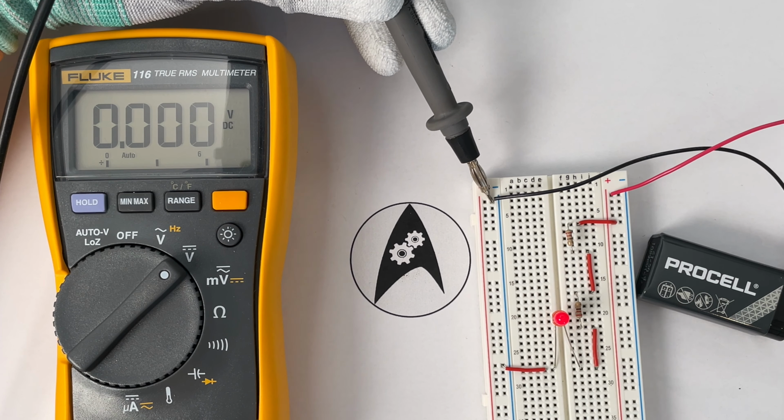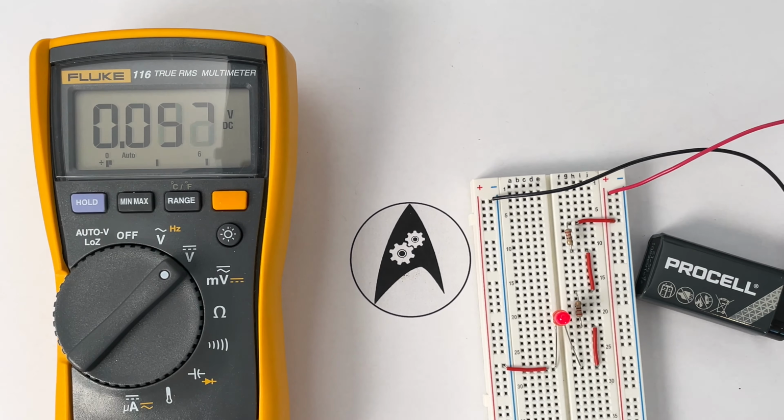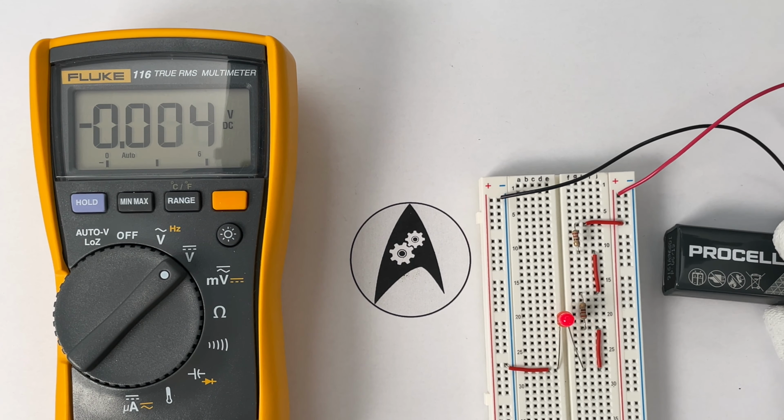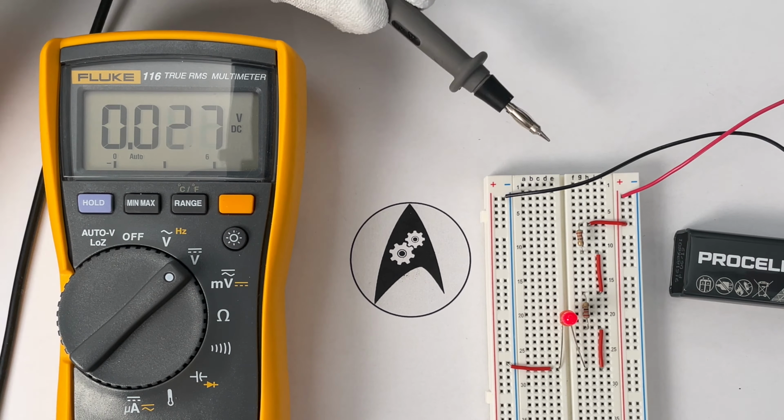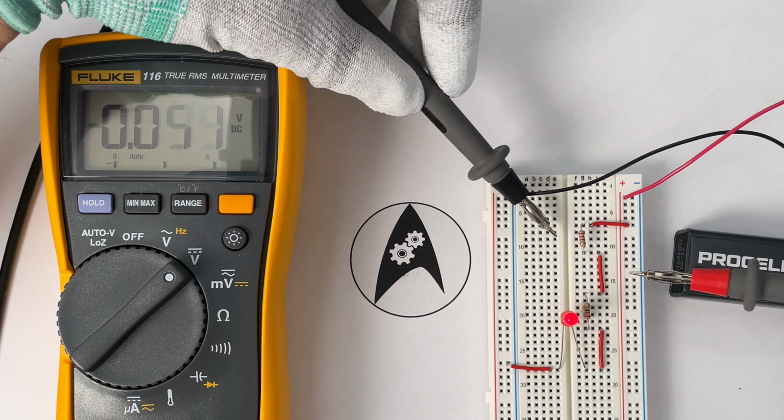Now let's talk about voltage. Voltage is always about a difference between two points. Voltage and potential can be identical if I choose voltage to be measured between, let's say, an arbitrary point on the circuit and the negative terminal. That's both a potential and a voltage, but I can also use voltage to express the loss of potential energy across a certain element, such as this resistor here.